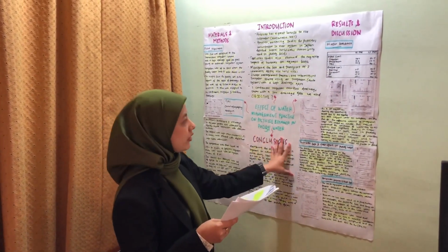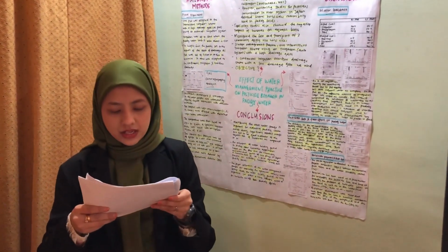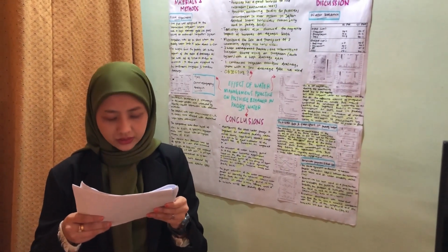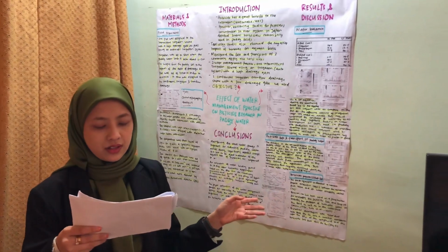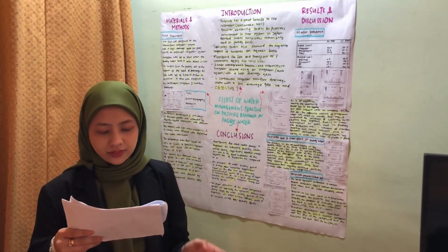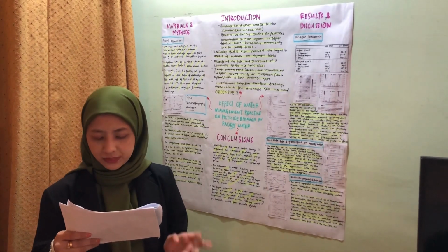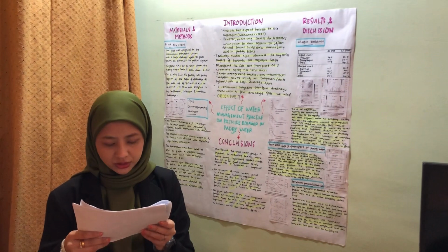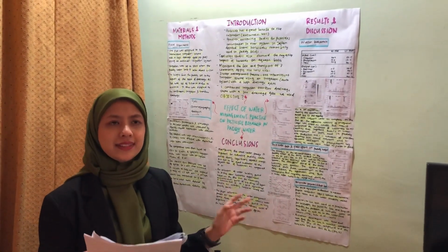However, the average value of the measured percolation rate, including this hotspot, is consistent with the monitored data. Some points with a higher rate were also observed along the concrete bank of the plots. That means seepage and/or underground percolation may contribute a significant portion to the water flow at this point.